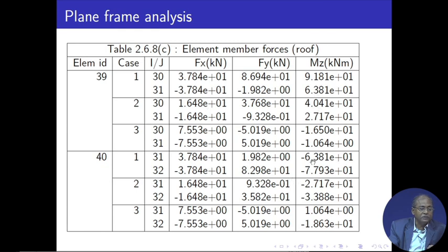So, from all those things you can get the maximum bending moment and maximum shear force for that particular section, and on the basis of that you can find out. If you have done this, then you are through. Now, out of this analysis, as I have told you, your live load may be different; I have considered all the floor loads the same. Because of that your values will be different, but if you write a program for all those things, it is very easy to solve.